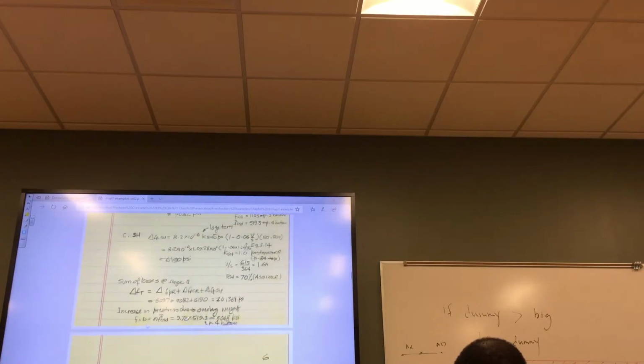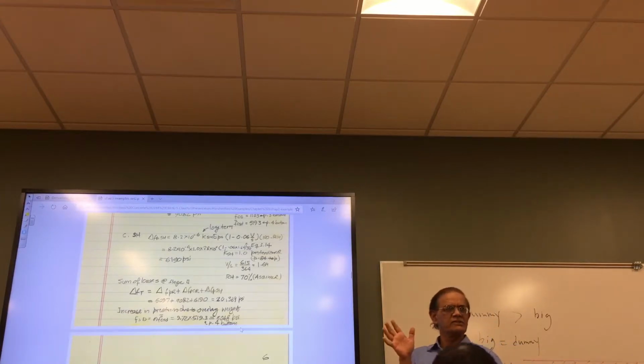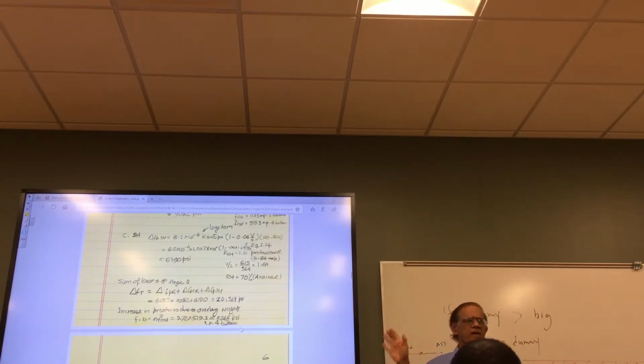Then what we have done is this number, 5,048 psi, is going to be the same for post-tension, more or less. In the post-tension calculation, we use the same number, although it will not be exactly the same because in post-tensioning there are a different set of losses. So your pre-stress force is not the same at 30 days. It's kind of a rough calculation, but remember this 5048.